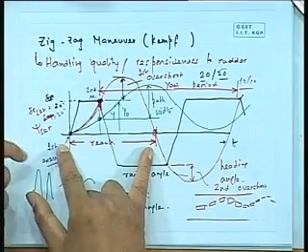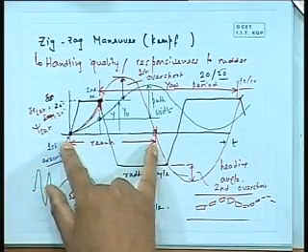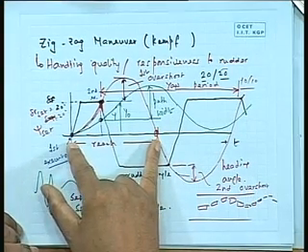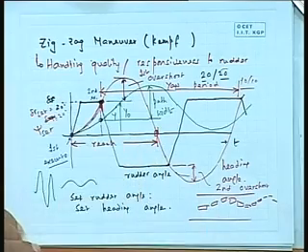Typically I will tell you again from this diagram, you probably should write down, reach will improve with rudder effectiveness, means this time, how fast it will come back, how fast it turns. The quickness of turn obviously will be more if rudder is more effective, and obviously will be less if the ship is very stable directionally, because as in some book I read, it's like a dogmatic mule, it doesn't want to change, it just wants to go along a straight line. So therefore it will take a long time to turn it back.